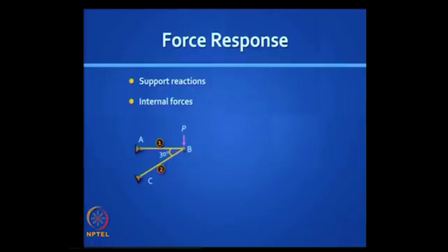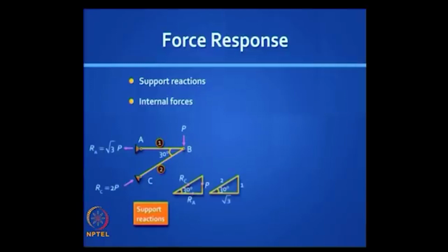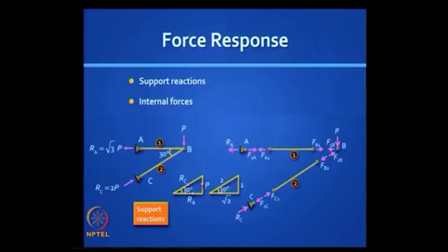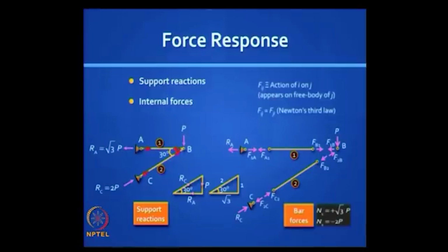What do we mean by force response? Well, in a truss, it means you need to know all the support reactions and all the internal forces. So if you take the overall free body of that truss subject to the load P, it is easy to calculate the support reactions. You can use a triangle of forces if you wish, or you can use direct equilibrium. But if you examine very closely that support, if you separate it out, you have an action and reaction coming into play. That is Newton's third law. So you must realize that there are many forces coming into play, but they are really related to one another, and you must know how to appreciate the different forces. Okay, this is elementary.